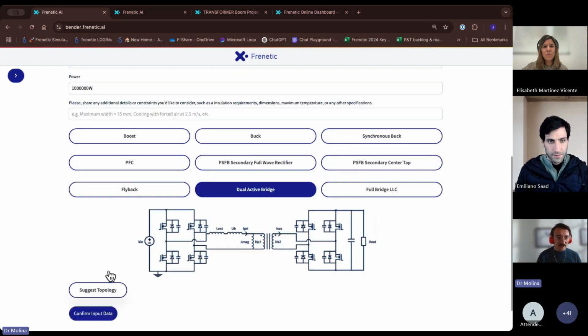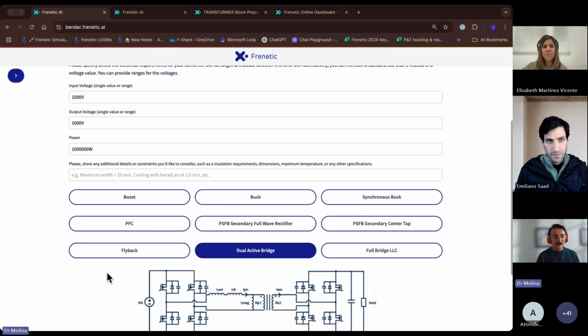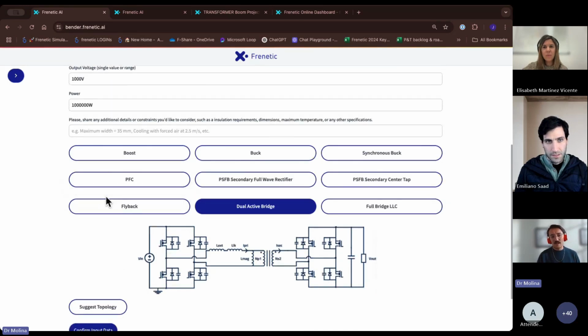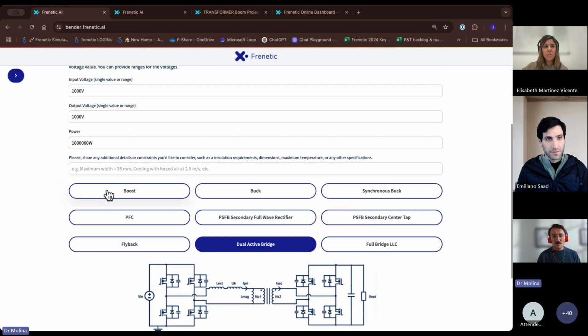I'm not going to run it, just to allow the people to participate doing these kinds of things. But it is as simple as this. Now you have to check if the results make sense and run the simulation in LTSpice. And that's all. Also, once you are playing, you will see that sometimes you will need to, for example, limit the turn ratio, or the magnetizing inductance, just to make the design simpler. Hope this is clear for you, Vito.